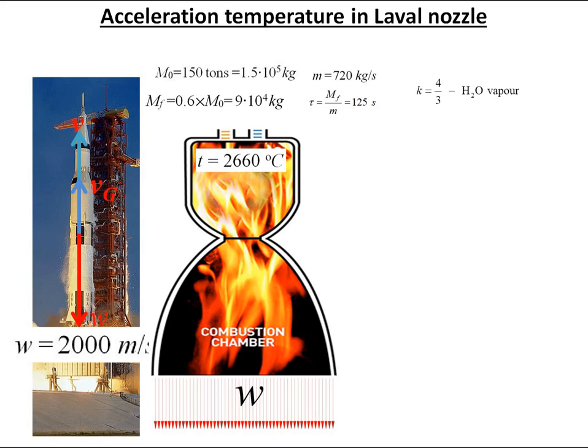From this maximum temperature in the combustion chamber, gases very fast adiabatically expand, and at the entrance to the Laval nozzle we assume that the temperature will be about 2100 degrees Celsius. Okay, we are entering a guessing game, but this is partially true. First, the combustion chamber must have enough volume to allow a controllable explosion and expanding gases to decrease in temperature, but also not allow the temperature to decrease too much.